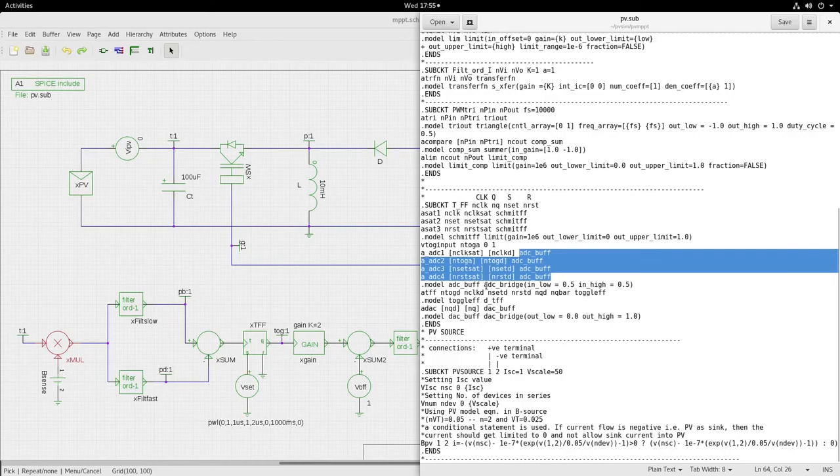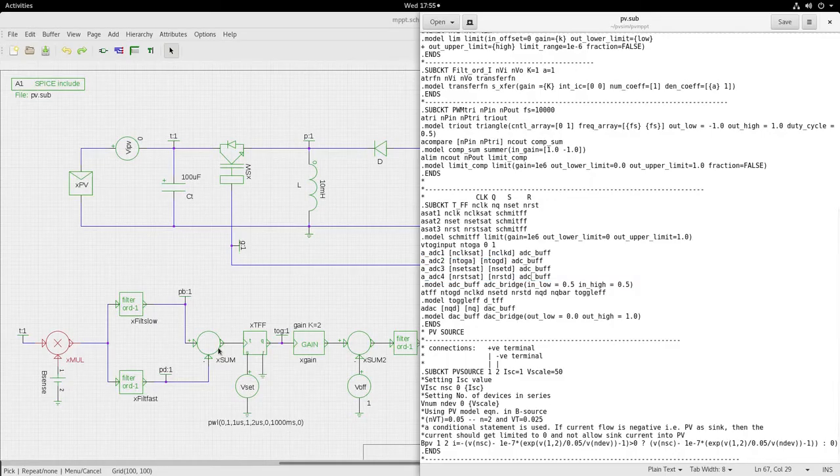It's an ADC bridge. Every analog signal has to be passed through an ADC bridge before it is put into the digital domain. So in any mixed mode simulation, keep this very important thing in mind. Any analog signal, pass it through an ADC bridge, take it into the digital domain and do the digital domain operation here. Model of the toggle flip-flop is D_TFF.